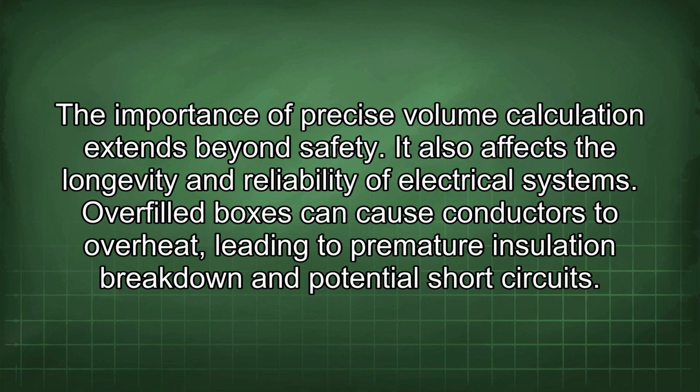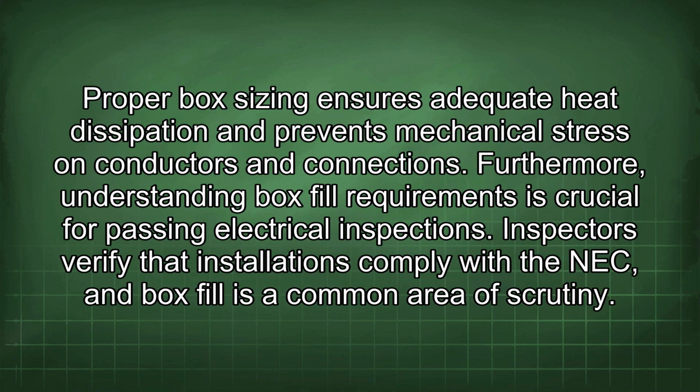It also affects the longevity and reliability of electrical systems. Overfilled boxes can cause conductors to overheat, leading to premature insulation breakdown and potential short circuits. Proper box sizing ensures adequate heat dissipation and prevents mechanical stress on conductors and connections.